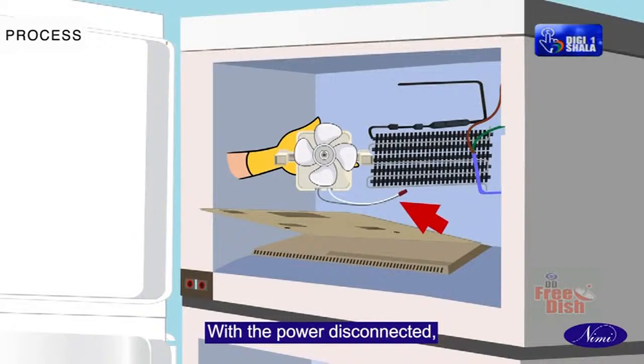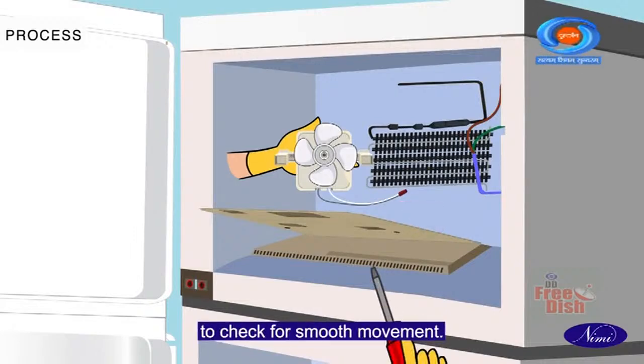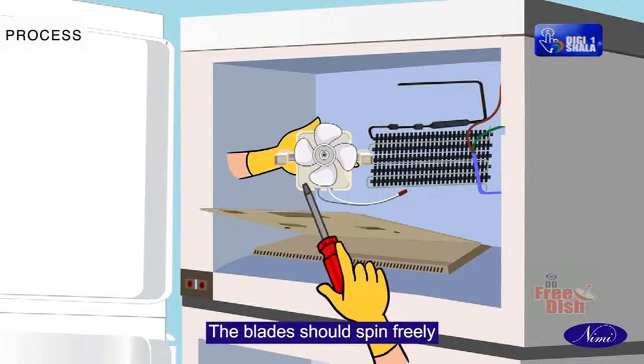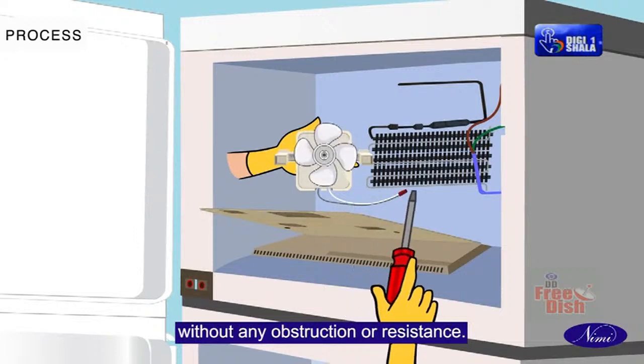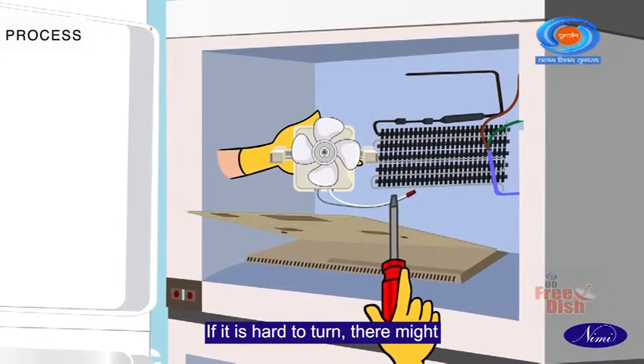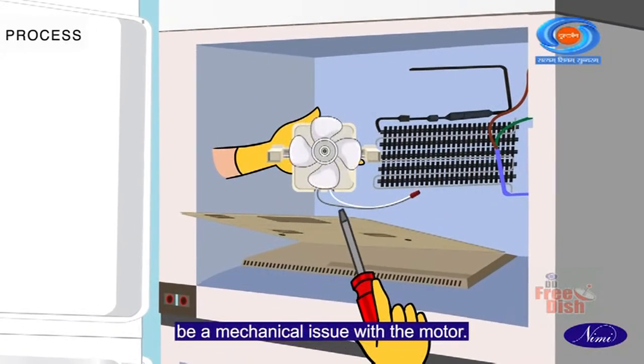With the power disconnected, manually rotate the fan blades to check for smooth movement. The blades should spin freely without any obstruction or resistance. If it is hard to turn, there might be a mechanical issue with the motor.